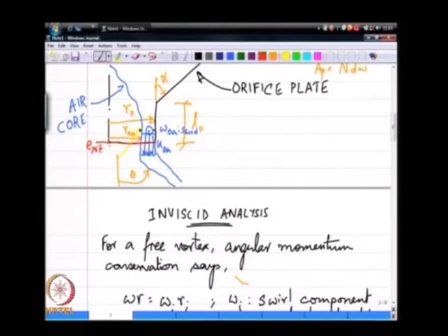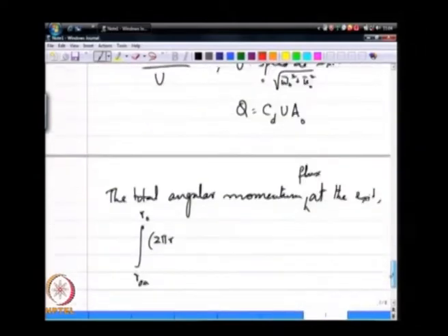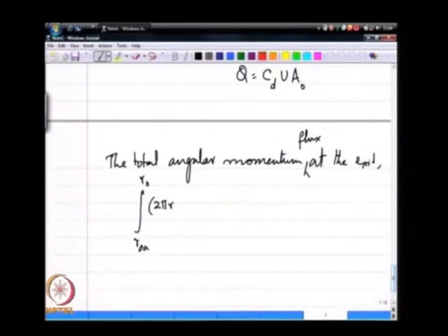So, the exit is essentially the mass flow rate times the angular velocity associated with the mass flow rate. So, I have 2 pi r rho u0 bar dr. U0 bar is the mean axial velocity. That axial velocity is actually what is carrying the mass out of the nozzle. The swirl velocity is not carrying mass out of the nozzle, because V dot dA, which we are used to in control volume analysis, for the swirl would be 0.